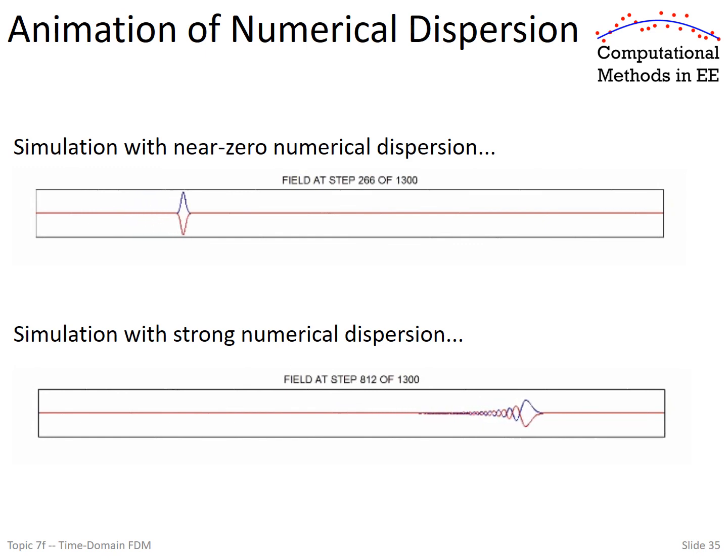So that's called numerical dispersion, and all time domain algorithms will suffer from something similar to that. And we really need to take care when we set up our grid parameters and time steps to ensure that that artifact is small enough that it won't cause any problems. The simulation or the movie that's happening at the top, there is still numerical dispersion there. It's just small enough that we don't observe it over the scale of our simulation. So in a practical sense, we've eliminated it, but it's never eliminated. It's just reduced.